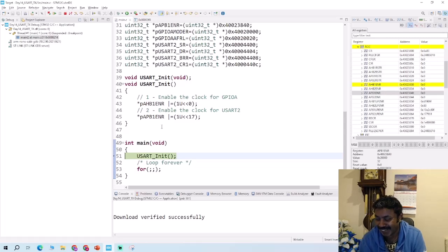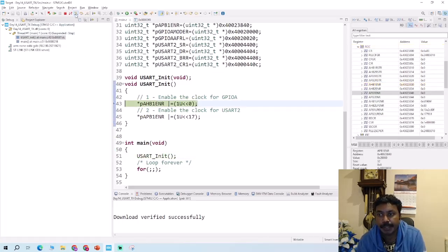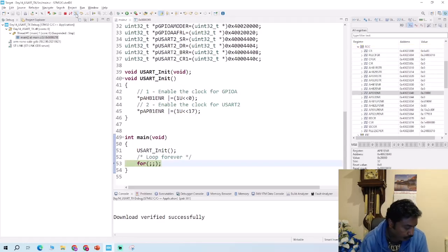I was about to capture the LED status, but yeah, okay, never mind. So now AHB1, so going to step into APB1 ENR, AHB1 ENR, and this should change AHB1 ENR. It updated 01. So the next one should go as well to APB1 ENR, 0th bit. What did I do wrong? I think I did the port declaration as 17. Yeah, 1U shifted by 17 should be 1.